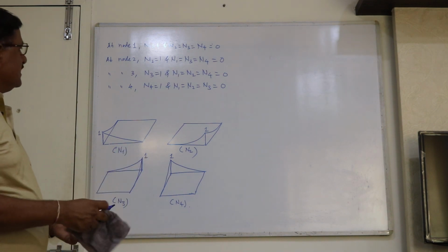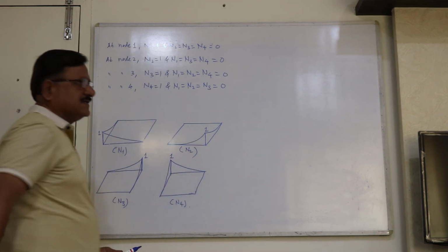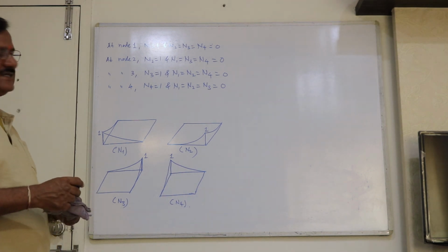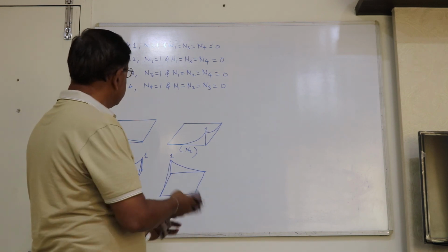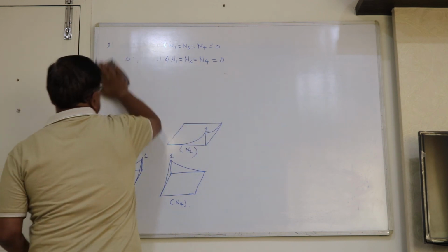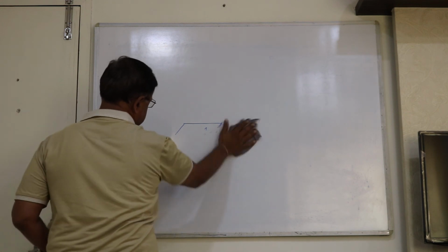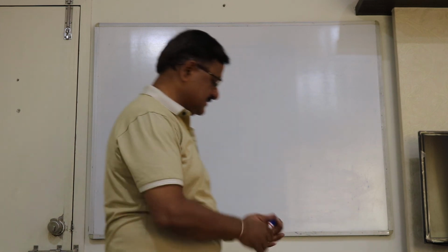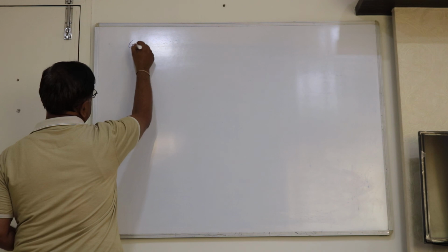Now next, we have to express the geometric functions in terms of the same shape functions. Let's use the same shape functions to define the geometric functions. In order to derive the element stiffness matrix, we have to find the strains and stresses, so that's why the geometric functions are required.